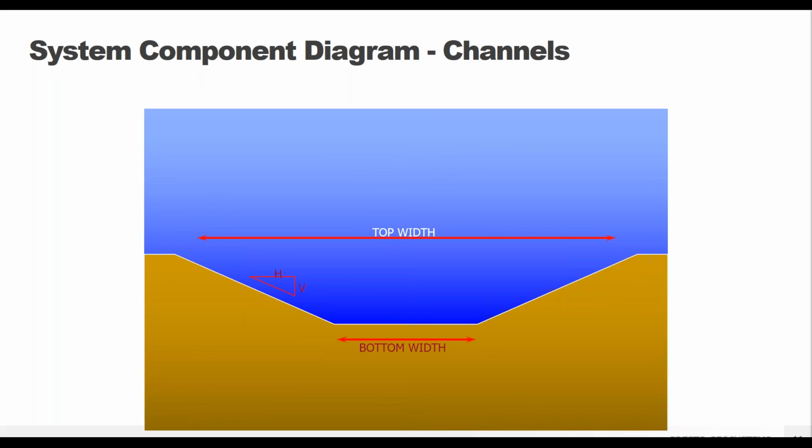And I do want to stress, when I say the word channel, I am talking about protecting an area that's going to see water flow. This could be the full width of the channel, so the channel bottom plus side slopes, just the channel bottom itself, or even just the side slopes, or a slope structure such as an embankment or a dam. So really you have full flexibility here of where you want to place the GEOWEB panels for your project.